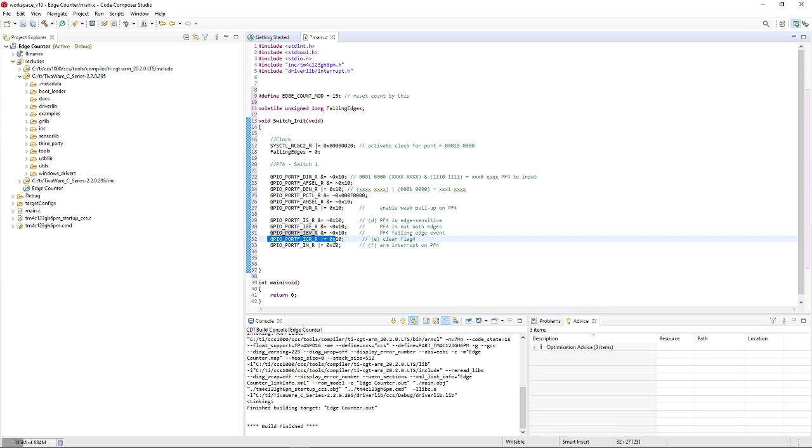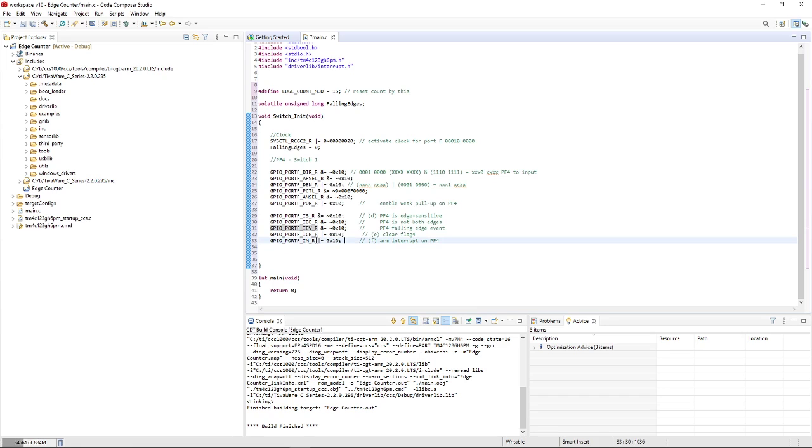This clears another important register called the RIS register, which just tells us if there's been an interrupt on a certain port and where on that port it occurred. And then this register right here is the arming register. When this is set to 1, it tells the CPU that we do in fact want to trigger interrupts from that device on that port.